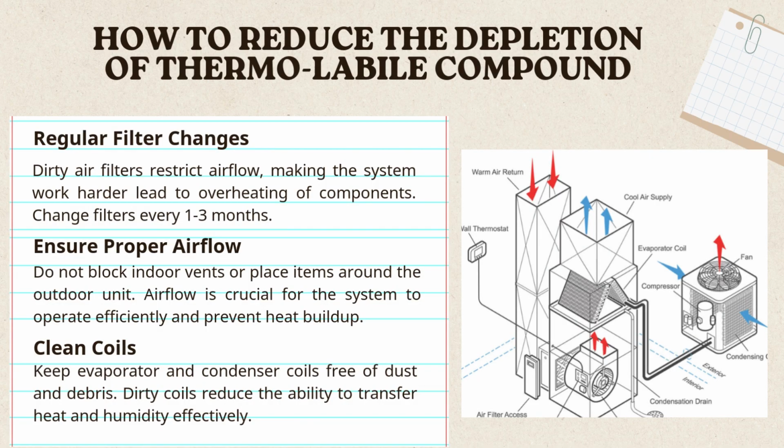Next is ensuring proper airflow. We have to make sure that the indoor vents are not blocked and nothing is placed around the outdoor unit, because good airflow is essential for the HVAC system to remove heat efficiently.